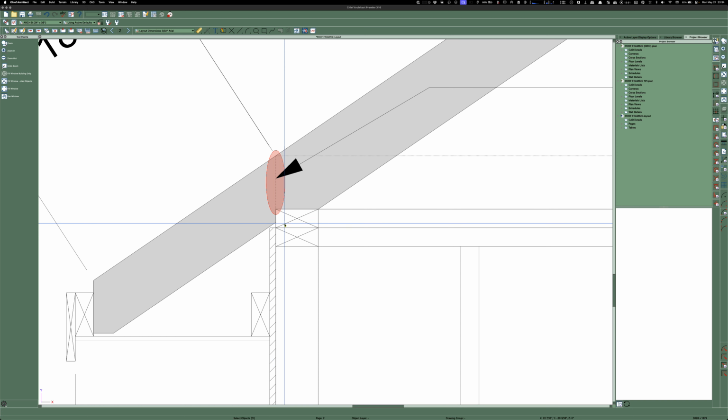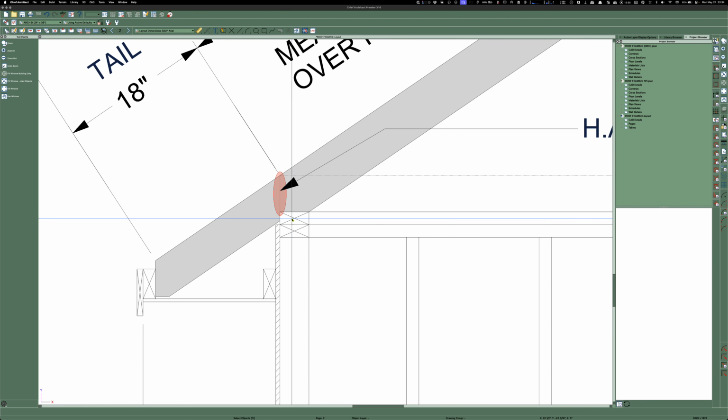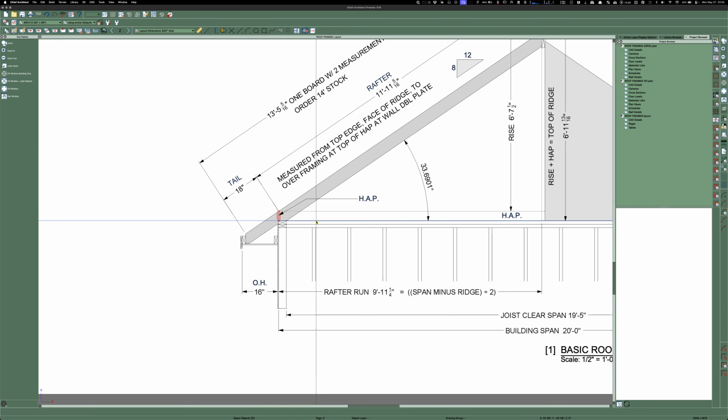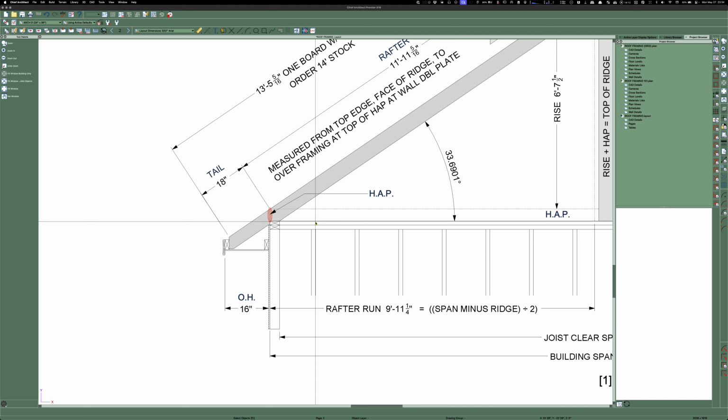I realize that some of the guys, like, who are they? Awesome Framers. In some instances, they get rid of this second double plate, and they'll just use metal strapping. It's authorized by the code or engineering, either one, to connect this wall to this wall. It's totally acceptable. I'm not a big fan of losing that double plate, because if it's a wall that's 8 feet high, now you're not going to get your sheetrock in there without having to cut your sheetrock to fit.